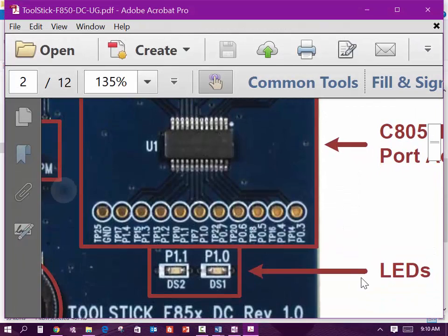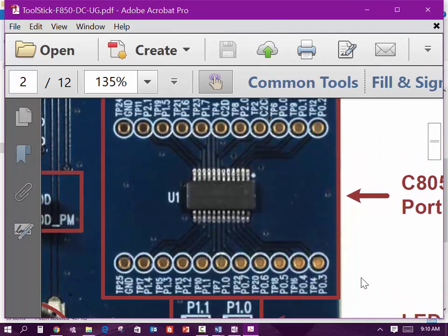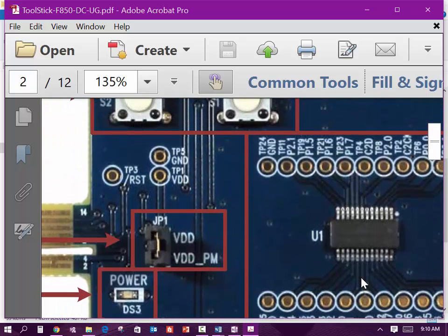right here, they don't bring it off here. They've got the ground. You also got to bring ground off too. Actually, yeah. No, you don't have to bring ground because you don't have to connect anything to ground. But the 3.3 volts comes off right here. Hopefully she's got that connected up that there. So the 3.3 is going to come off of that there. Actually, we tried doing that with the LCD, as we recalled, and the LCD would not use 3.3 volts. So the 3.3 volts will come off of there.